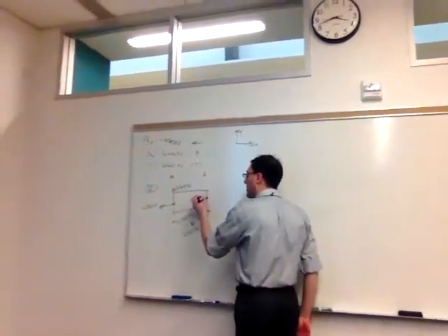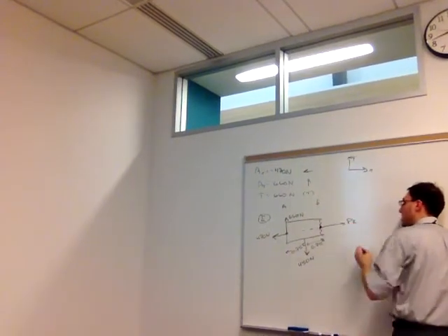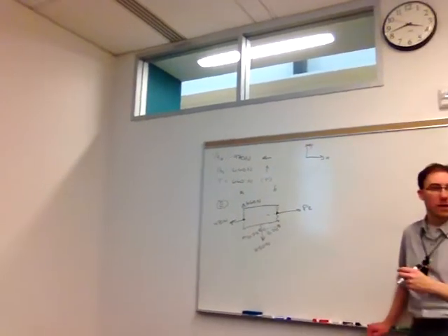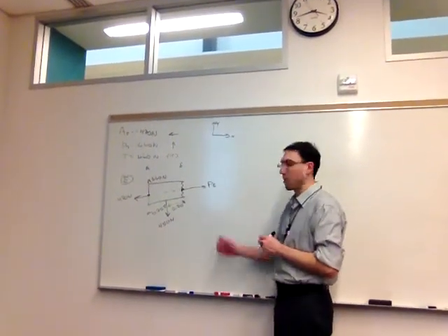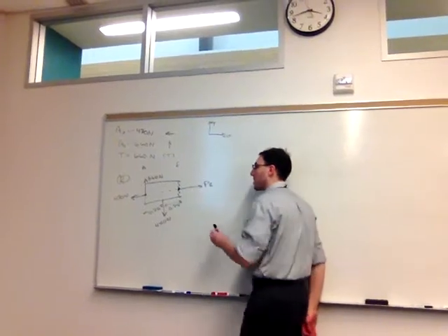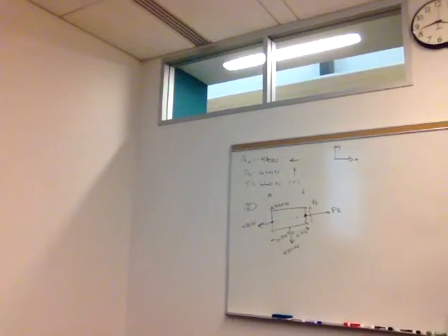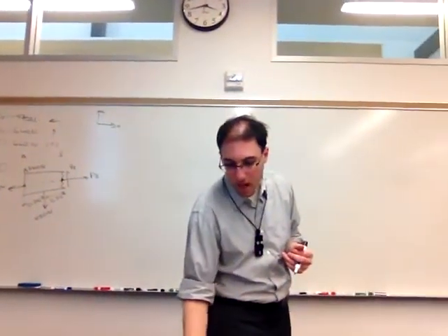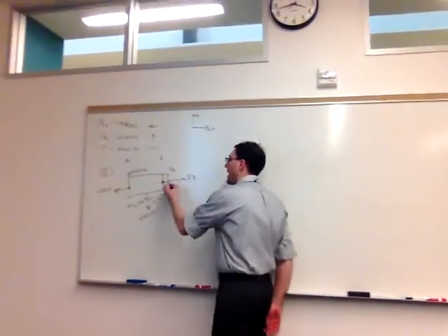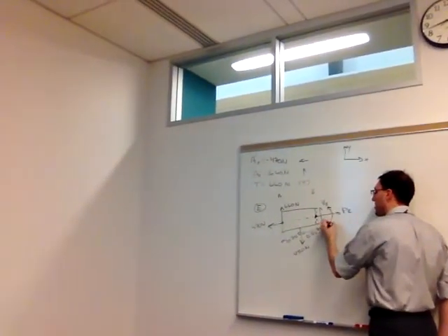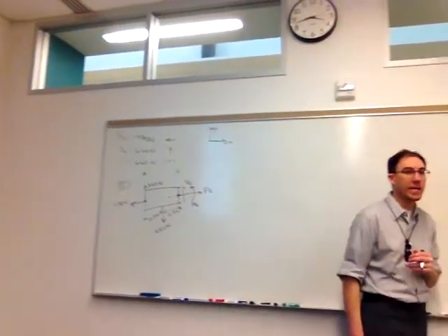And then where I cut through the material at point E, I'm now going to have that internal normal force I'm going to call P sub E. I'm always going to draw it coming out from the surface of the cut and always orthogonal to that surface. I will have a shear force. I'm going to assume that it's up. That V sub E. And an internal moment, internal bending moment, I'll call M sub E. And I'm going to assume that that is counterclockwise.